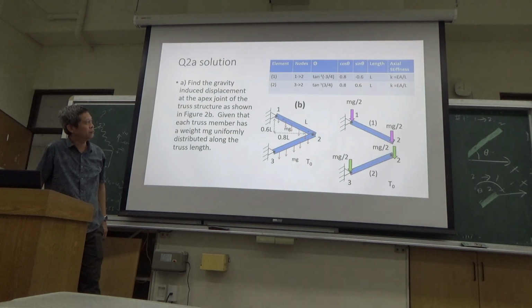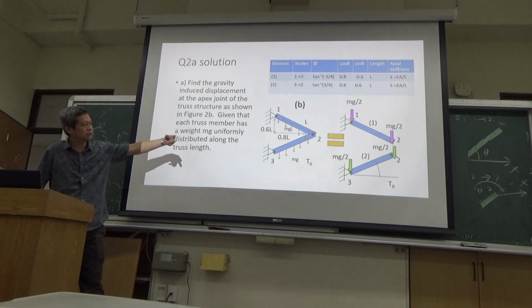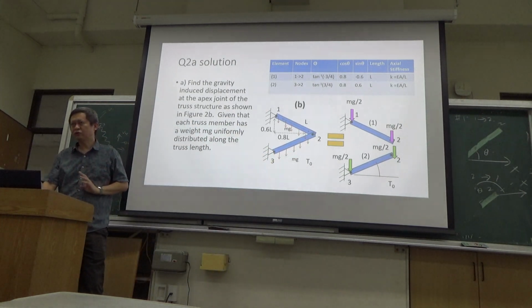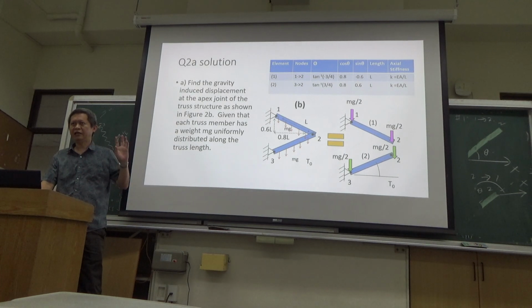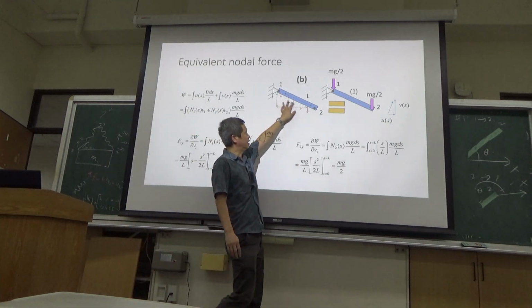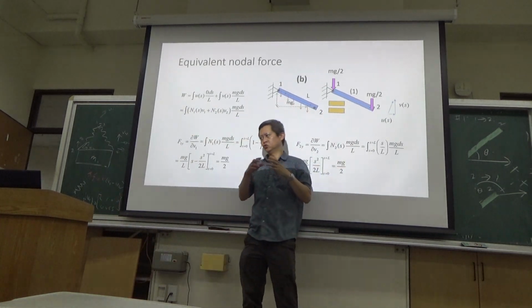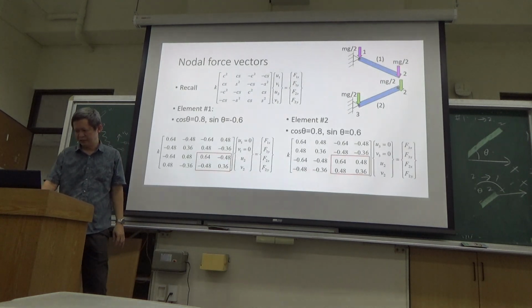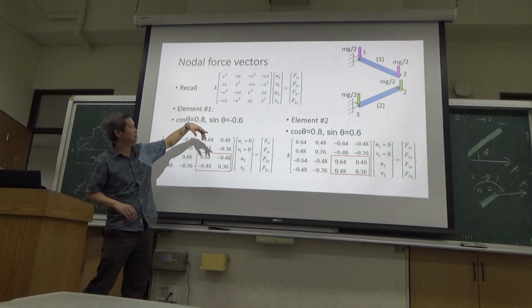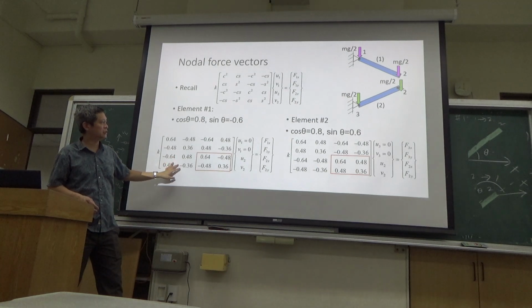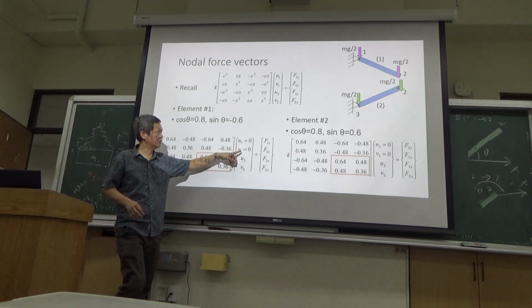So this is the sort of problem that we solve. I think later we will come back to how you handle a truss with distributed force, because in our modeling so far, you handle springs, and a spring can only handle longitudinal force. A distributed force acting on the truss is equivalent to a pure truss with two normal forces. Then since you're going to have two trusses, each of them you can use the equations, and in the operations you do the calculations, and then you apply the constraint on the boundary.